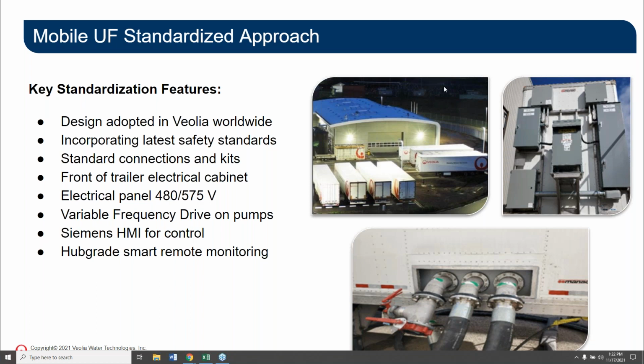So you have a chemical preparation semi-automated sequence, a cleaning sequence, a neutralization sequence, and the operator can even force a hydraulic clean of a specific skid when required. The main facility of the asset is the mini CIP chemical cleaning facility. It's basically nothing but a shorter CIP.